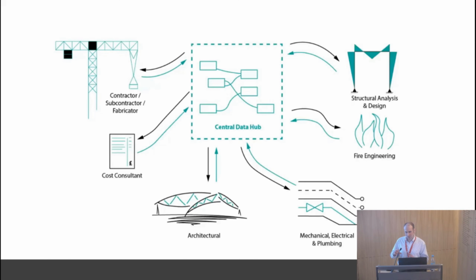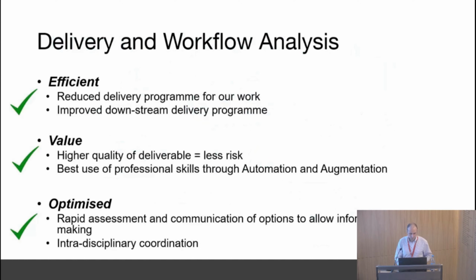So you can start to build in parameters to your data sets where actually you're limiting the size of components based on your crane capacity. So something we did on Hong Kong, for example, is effectively an automated routine where we're looking at the maximum size of components which are transportable. That locates the splice, and you're then optimizing that structurally within those parameters of what is transportable. So you're just layering in that data and optimizing it that way. And then it's basically ticking all of those boxes.